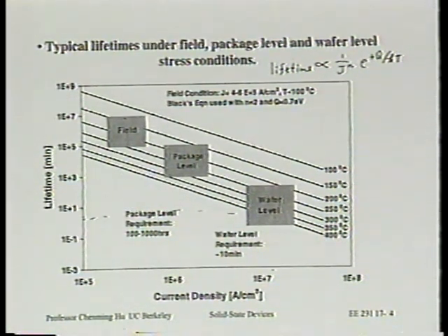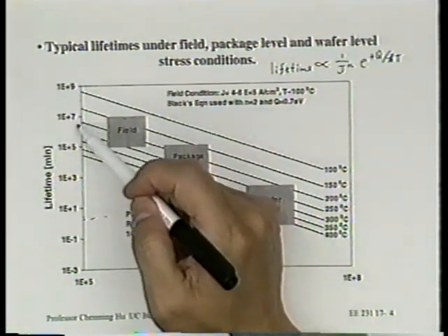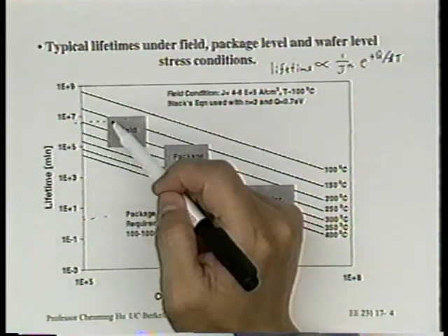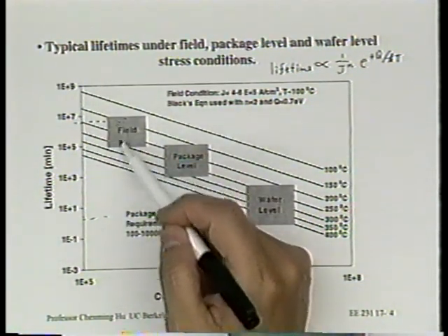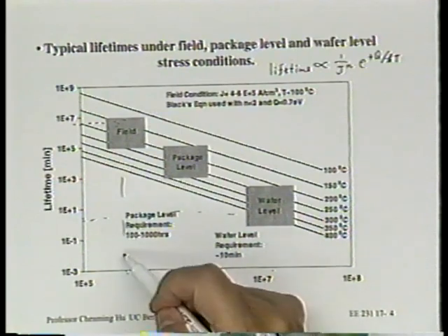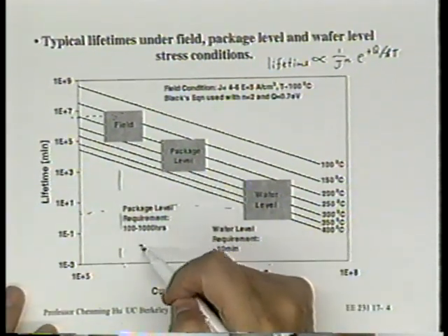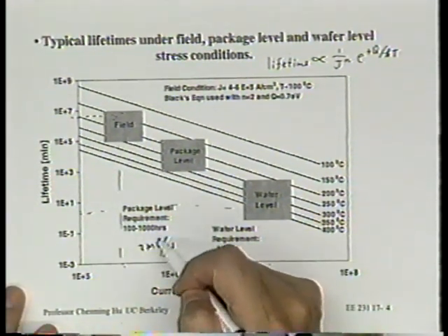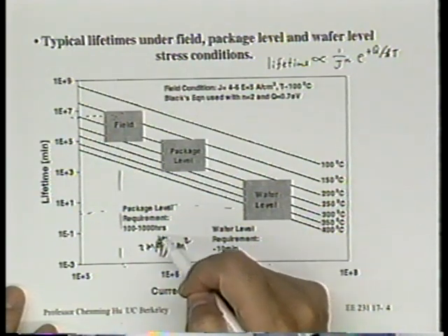Okay? All right. Actually, what really happens is kind of reversed. The reliability engineer does not take the current density from the designer, but performs this experiment first and comes up with a number saying our metal technology is good enough for, let's say, 2 milliamps per micron squared. And gives this number to the designers.